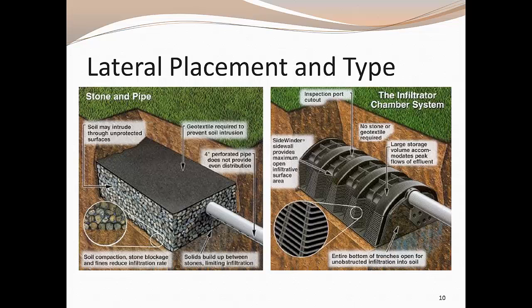An alternative to the typical gravel-filled trench installation is the use of engineered infiltration chambers, shown here on the right. Soil infiltration chamber soil treatment area installations are a viable alternative if the soil in the treatment area is suitable. These arched, high-density plastic chambers are open at the bottom and slatted on the sides. This design allows effluent to infiltrate into the soil directly from the chamber. Gravel is not used in this system. Infiltration chamber systems will work well where a conventional soil treatment area is also an option.